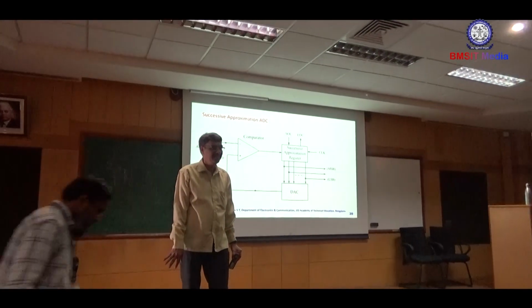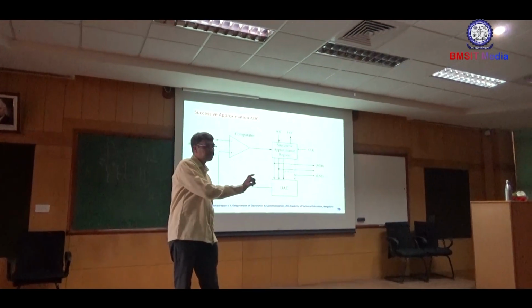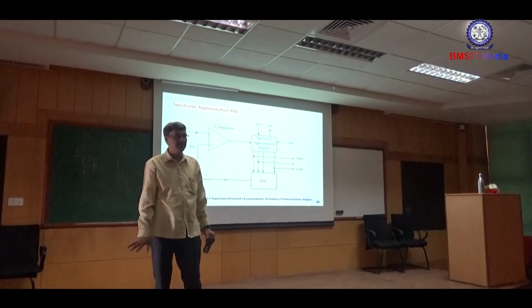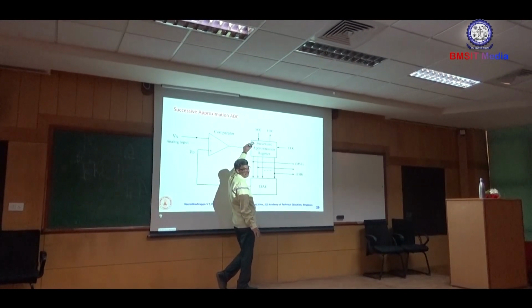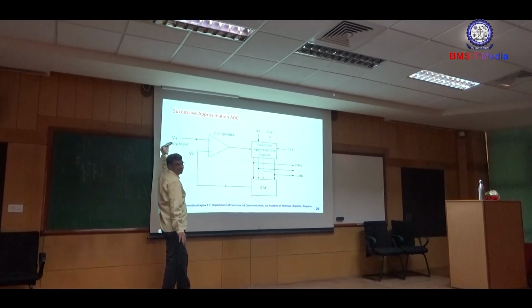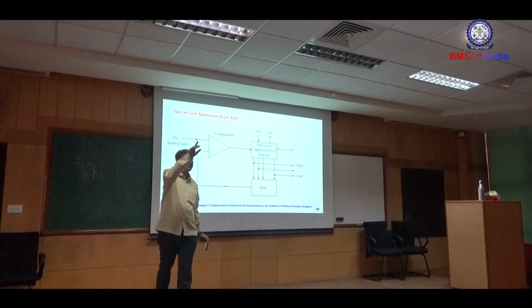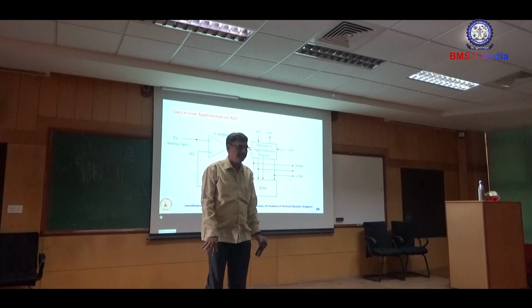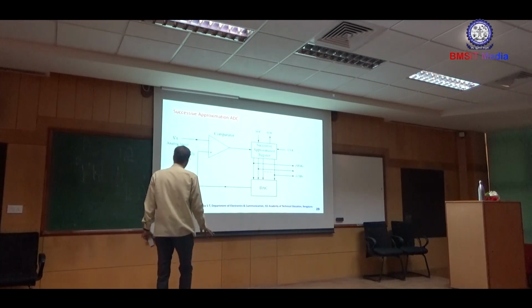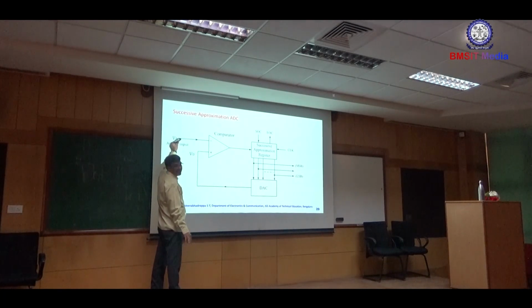How many clocks are required? The number of bits plus one for the start of conversion and one for the end of conversion. If you choose a start of conversion, now some input is applied, for example, 2.3 volts. With respect to the previous circuit, the values are minus 0.5, minus 1, up to 7.5 volts. This comparator is an open loop comparator, since this is VD minus VA.